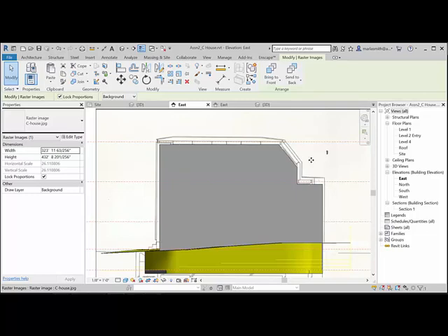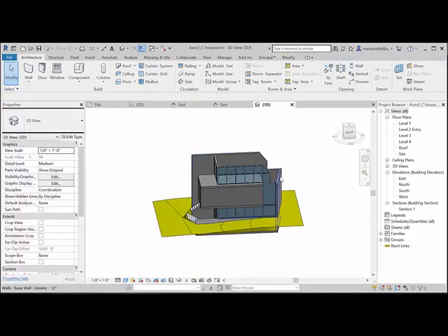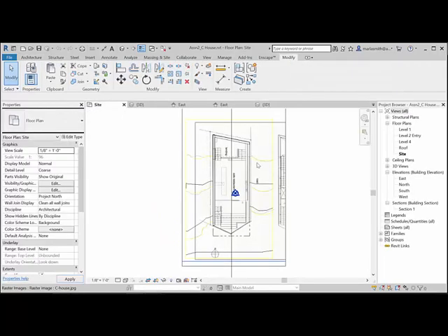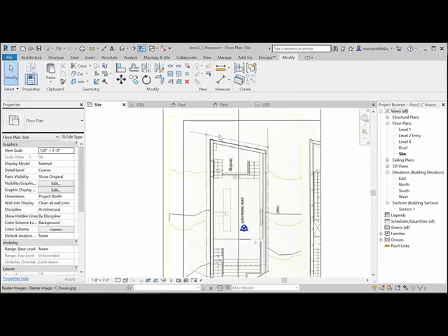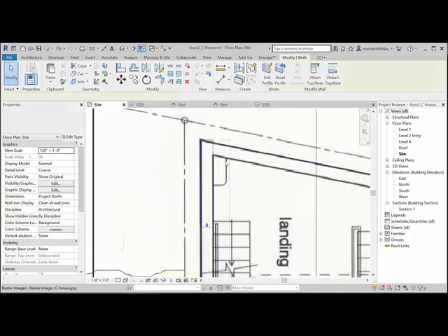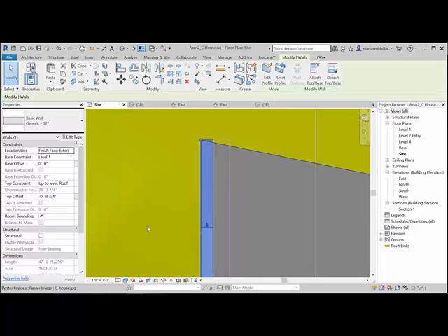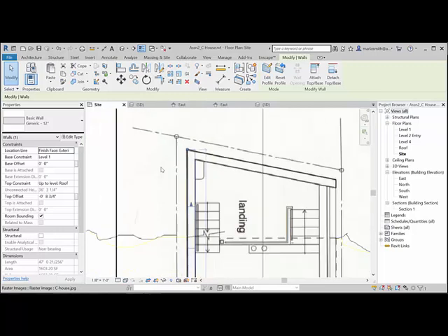All right, we've got our one side wall in, and now we want to go ahead and put in the back wall right here and the retaining wall. So if I go back to my site, I can come in, and here's the wall that I've placed right here, right? So I can pick that. If I go to shaded mode, I can see it a little better, right? But I need to be in wireframe so I can see my background.